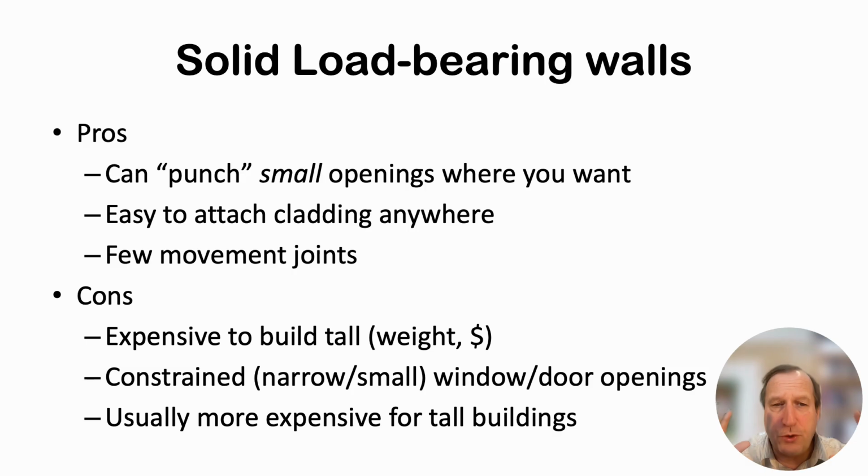The reason we don't do this as much anymore is that when it gets to taller buildings, this becomes quite a weighty and hence expensive solution. But just as important is that we don't want the restrictions about where we can put windows and openings and how big those windows and openings are. When I say we don't want it, the architectural designers, often the owners, do not want this.